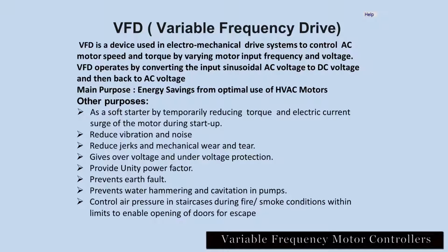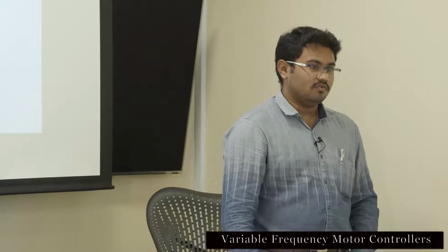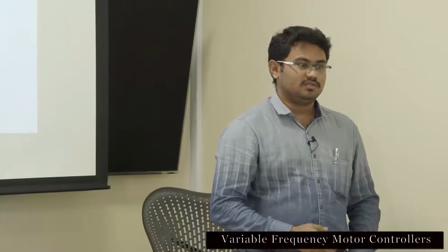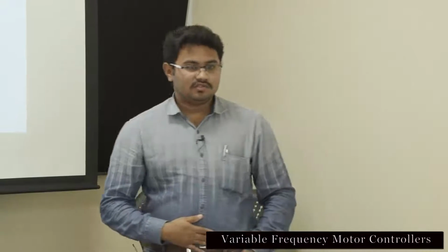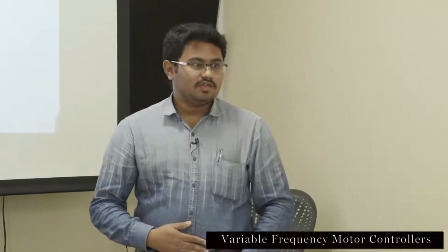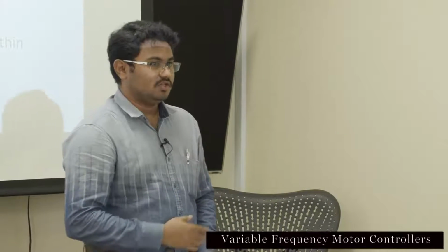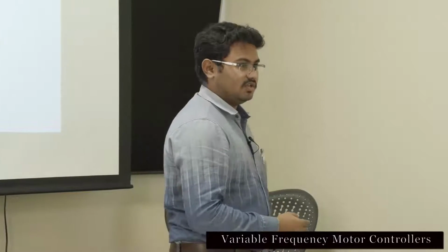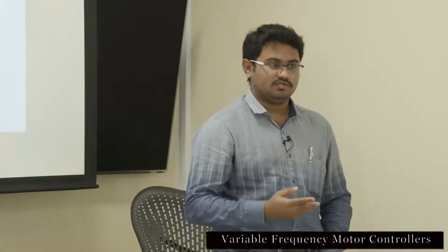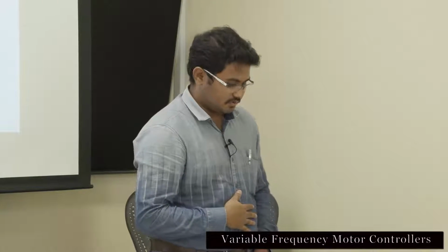So the variable frequency drive is mainly used to drive the motor at variable speed and variable torque applications, and in MTB we are using it mainly for pump and fan applications, where we are controlling the speed and flow based on the feedback from the PLC system. And the drive itself has PID control, which can control the process on its own. It doesn't need anything external, but just in case it can be incorporated.